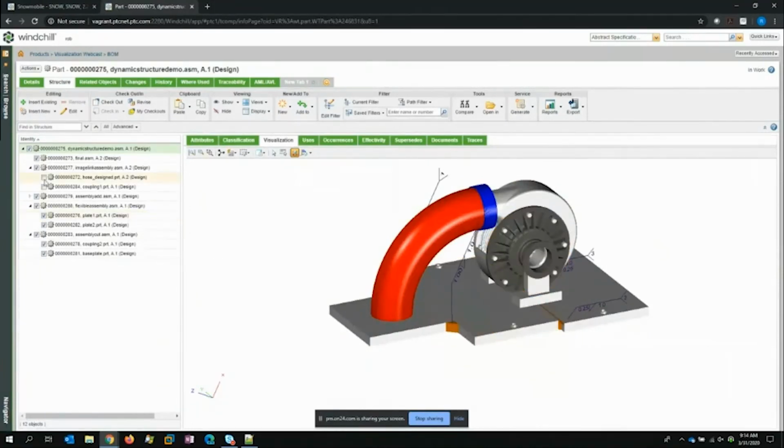What you can see here from the structure is that when I flag the CAD represented part, which is at this supplier part as well as this assembly that had the flexible component in it that I needed to be careful with, it gathered the representation from, in this case, it traversed an image association to get to this final pump assembly. In this case, it went to the default representation, but it stopped considering the parts in the structure. So in this case, I've lost any sensitivity to the content below it.